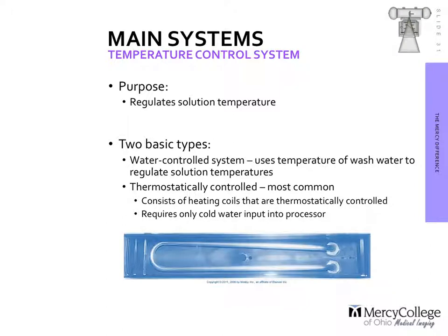So temperature, as you learned, is certainly key, and developer temperature must be maintained within plus or minus 0.5 degrees Fahrenheit. So it is very, very important. So this system is going to help regulate those solution temperatures.